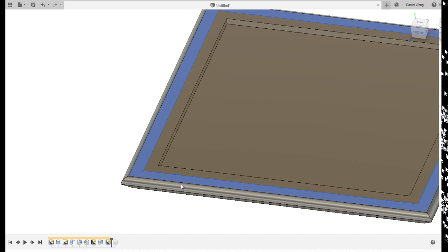And then once we've rolled back one step, I'll then go to construct and draw a sketch plane here and push it back 20 millimeters. Yeah? Does everyone get that? So I'm creating a new plane that's sort of displaced by some distance. Okay?